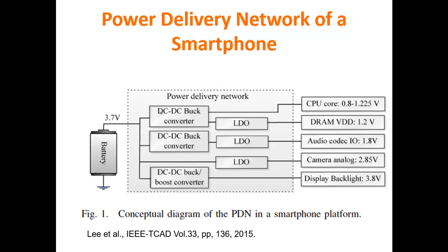You remember the issue: depending on the computational load of the CPU, we need a higher clock frequency or a lower clock frequency. And in order to have a higher clock frequency, we need smaller propagation delays and therefore a higher supply voltage, if you remember the equations that we obtained together. Which means that high load means high clock frequency, and therefore we need to provide a supply voltage of 1.2 volts in this particular example.